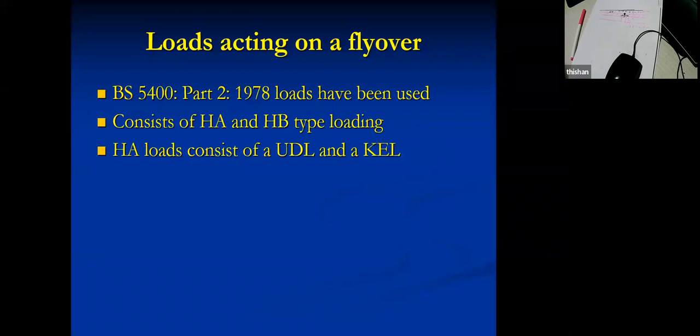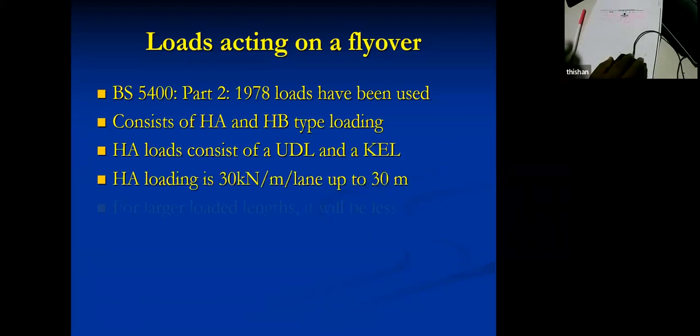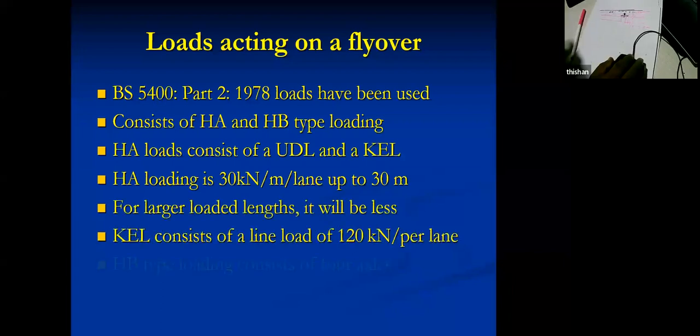You'll find this bar can be easily bent, but it's super strong. The reason is the interior still behaves like mild steel, and the exterior behaves like high strength steel. And because of that reason, the average strength can go up to about 500 megapascal or 500 newtons per millimeter square.